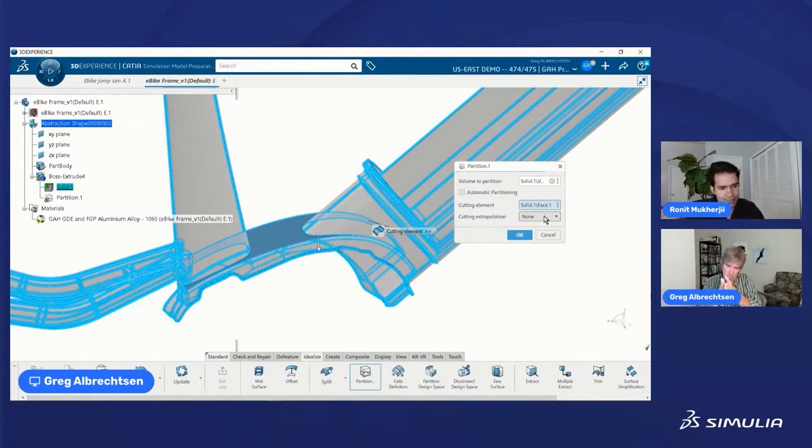And at that transition, because it's still mathematically one volume, it's going to merge all those nodes and elements right in that transition. So you're going to have all these really small elements hit that transition, and then it's going to expand out to the bigger elements. Yeah, and I'm going to do that same thing here.